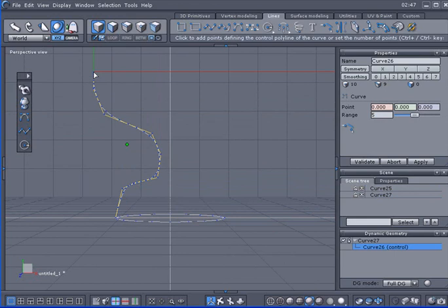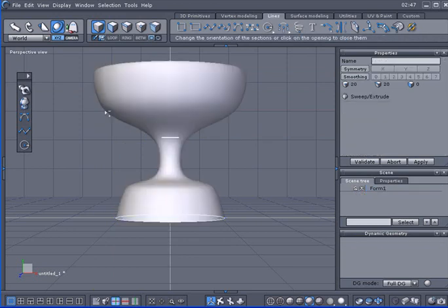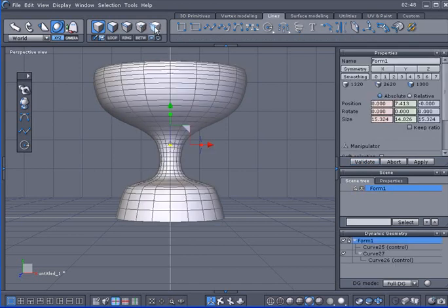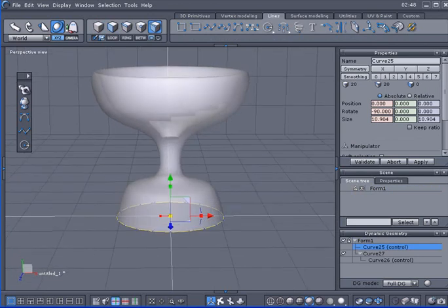Okay, this is when it starts adding volume, is when you start coming back down the line. Each time I click, that's a good point where you can alter it later. So I've been clicking, and I'll just double click to validate it. Select the shape, validate it, select the shape one more time, and we're going to go into auto select mode, and my transparency is on. You won't see it yet because I'm in select object mode. So when I select here, you can see it, and I can edit it.